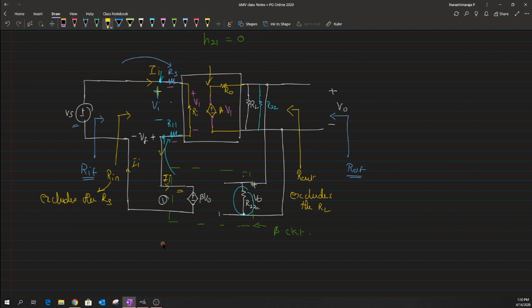Now I just want to bring out the different expressions out of this. The very first thing is that I also have to remove this, just because we moved our R22 to the basic amplifier. Now that we have made sure that this basic amplifier is cluttered with all different types of impedances, we have to recalculate all our input and output impedances of our basic amplifier.